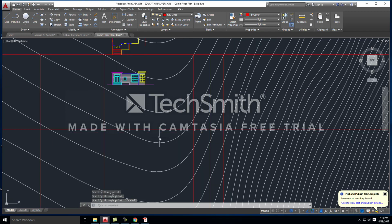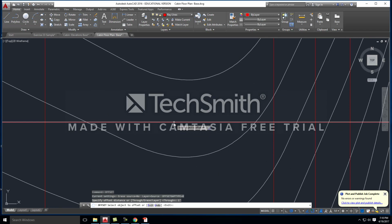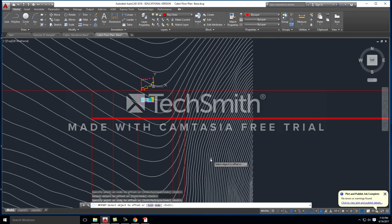Okay, and then from there I'm going to offset this line 1 foot. The reason why I'm going to offset it 1 foot is because each of these topography lines is a 1 foot elevation change. So I'm going to use the offset command, type in the distance to be 1 foot, and offset this line the same amount of times as I created ray lines up here at the top. So I'm going to have a total of 6 lines by the time I'm done. So 1, 2, 3, 4, 5, 6. All right, we see how we did that?